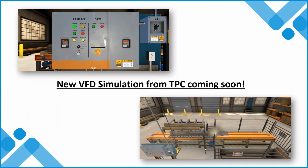Like I said before, you might have a shop bandsaw. Let's say that's real easy. Most shop bandsaws have maybe 3 or 4 different size sheaves on them so you can control the speed of the blade. If I put a drive on it, I can have either 120 or 240 single phase going into it. Of course, then I'm going to have to put a different motor on that bandsaw, a 3-phase 230 volt motor, and I can control that. I no longer have to change sheaves or anything. I can just use the potentiometer on the pad on the drive and slow it way down when I'm cutting, let's say, metal, and speed it way up when I'm cutting wood.